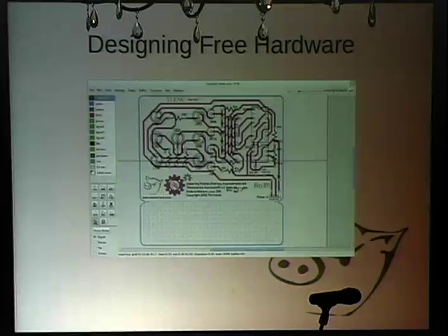But the process of making sure everything isn't overlapping, that you have the tolerances, you're still looking back at your data sheets for what you can and can't do. You'll have some components that say, you can't throw any signal line underneath my package, or I'm going to destroy it.